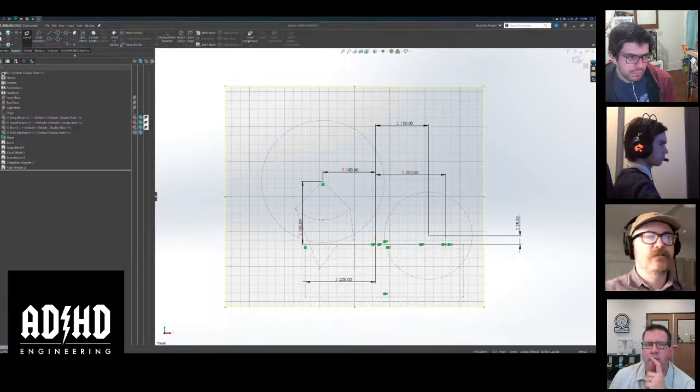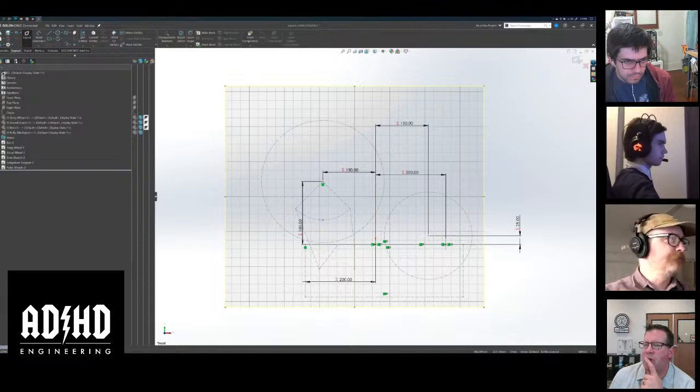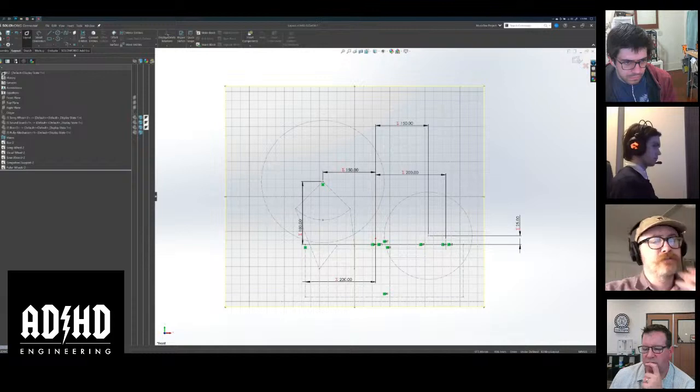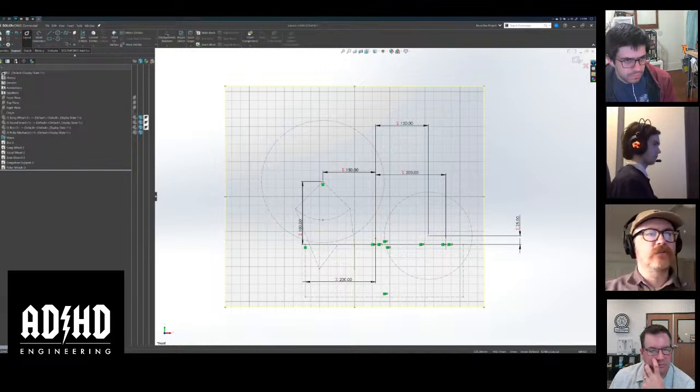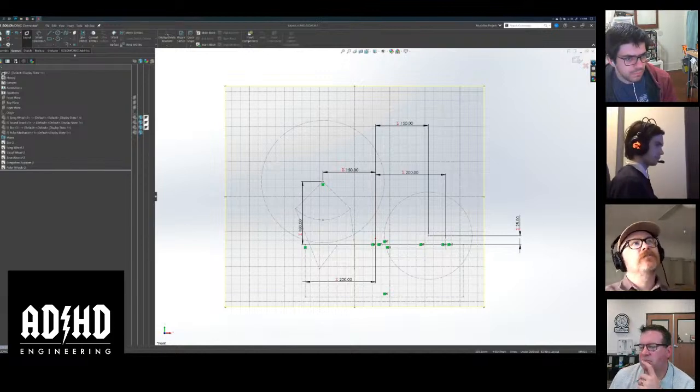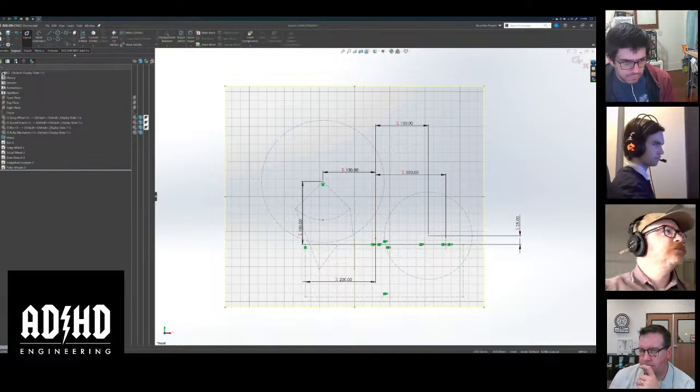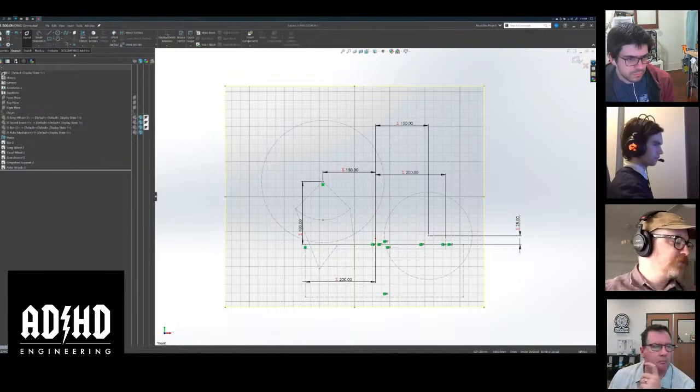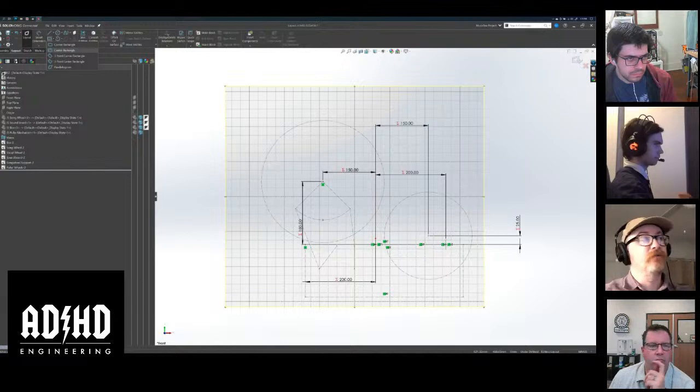Next, you said we wanted to put the motor in, all right? So we're in the sketch, and I'm just trying to think what format we could use for that. So are the bolt holes a square, and the center is the... Yes. Okay, so we might as well just use a center rectangle then. Yep. Because then we can actually do the bolt holes.